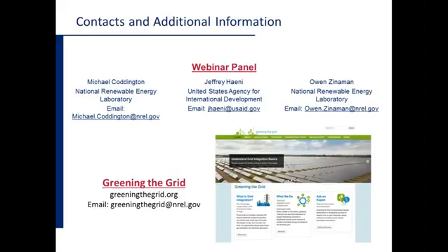But today what we're seeing are grid tie systems that really require the grid to be operational for them to be operational. So when there is some kind of emergency or an outage from the utility, the downside of these grid tie systems is that they go offline. And again, you need the utility power to be present in order to get the PV up and running again during the daylight hours, of course.